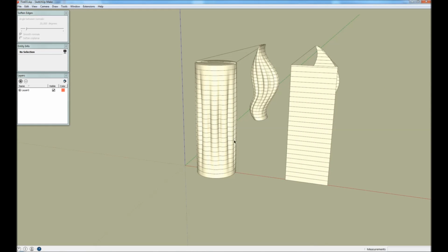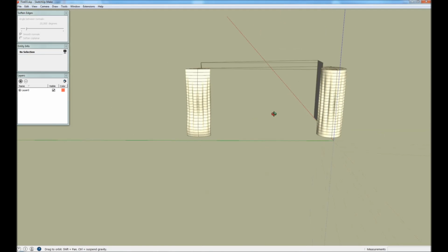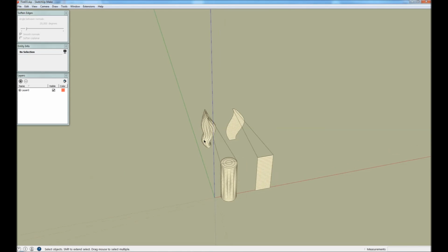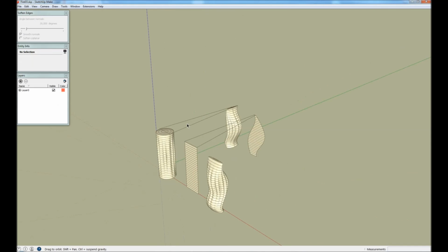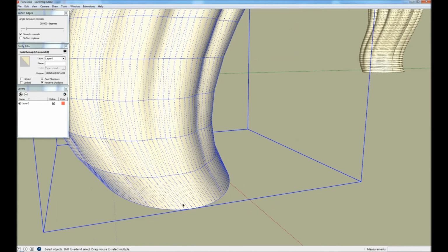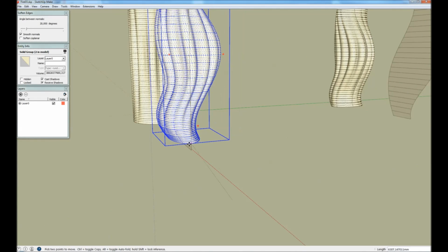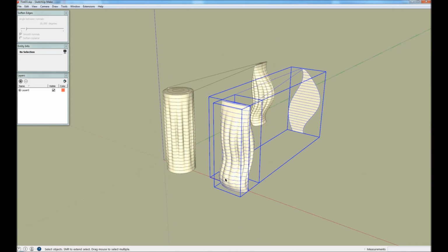So we have now remolded this shape, and it has assumed the shape of the target surface along this direction. But if we turn the camera 90 degrees, we can see that it is untouched along this direction. So we're going to use this to copy this geometry and then rotate it 90 degrees. And then place it on our other projection grid. So we find the extreme point, and then we place it. And then we select Flowify without cut again.